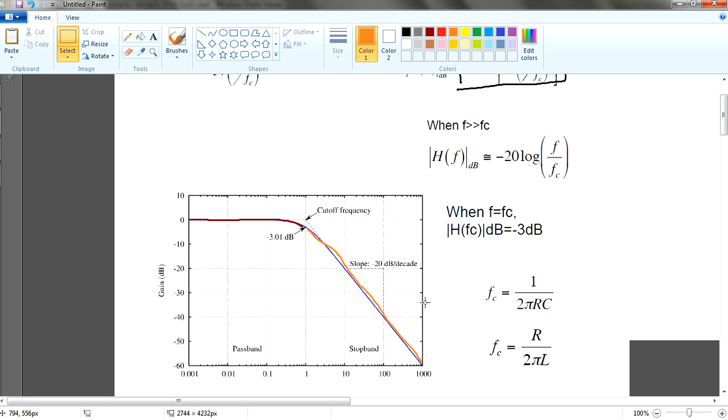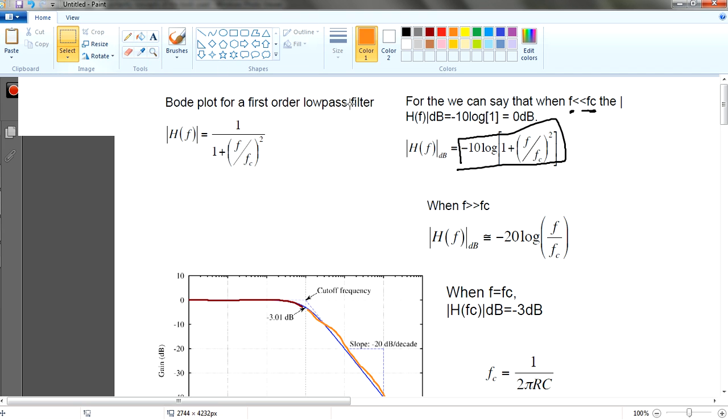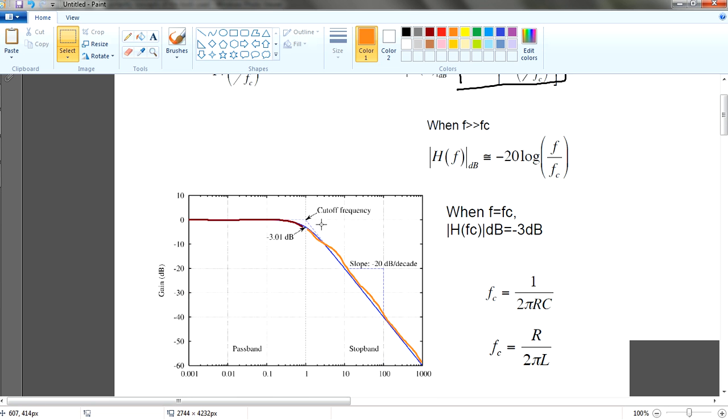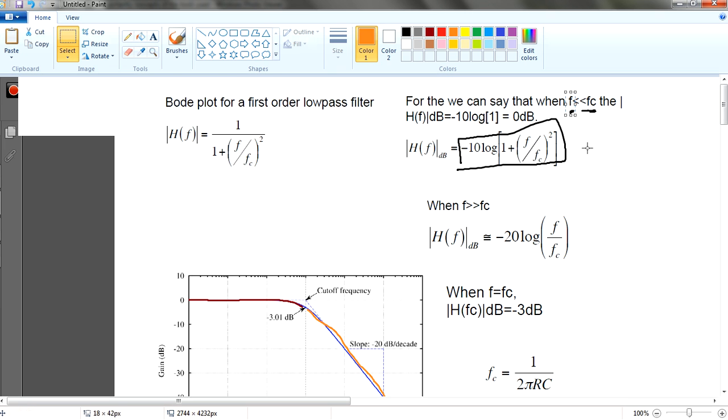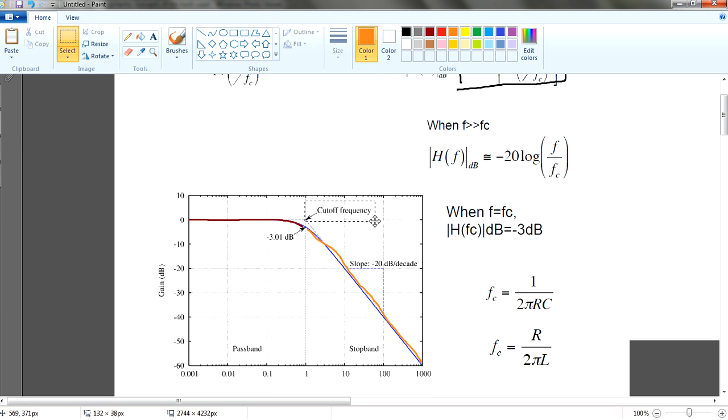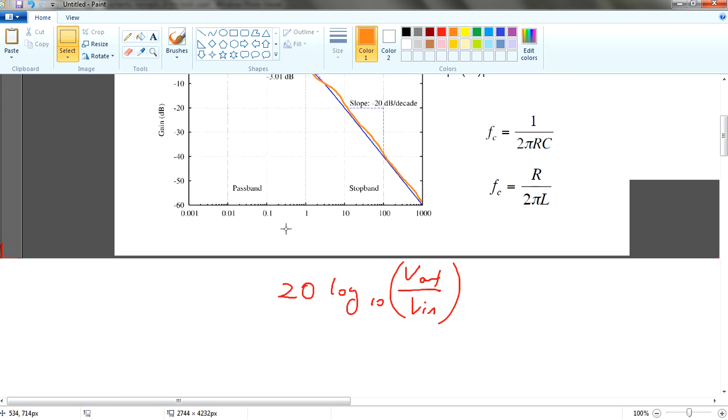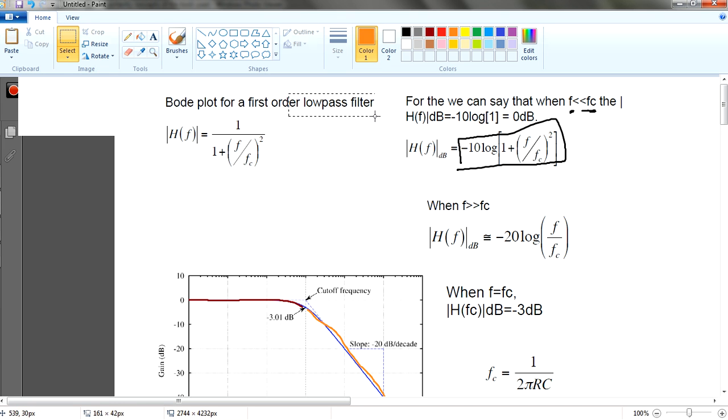What I'm talking about? What the hell? This is a low pass filter. This is a low pass filter, correct? So your low pass filter is going to filter out all the high frequencies, which is this one, right? So if your frequency is much higher than your cutoff frequency, you would go down and you isolate. So you only allow all the low frequencies to exist as this thing over here. So this is a very key concept that I want to convey for a low pass filter.